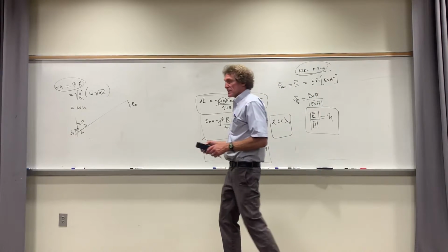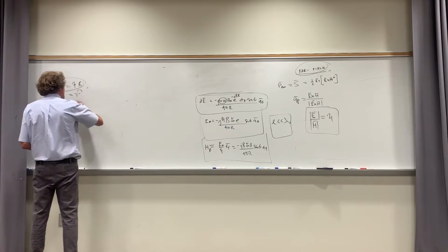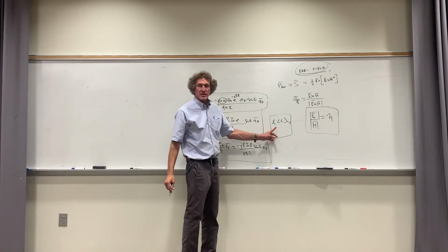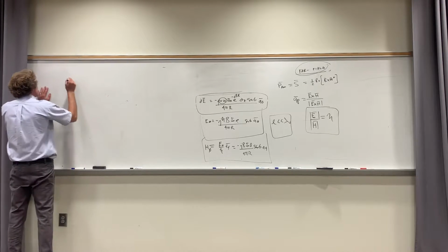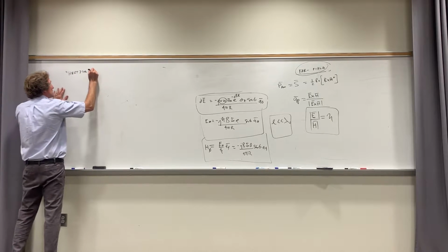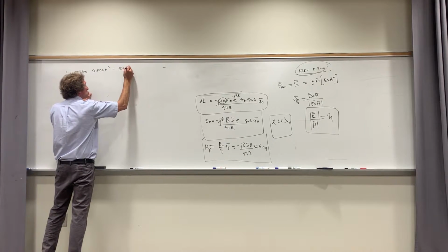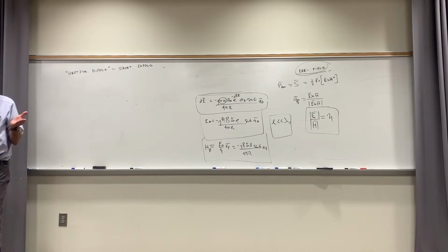Now, this is a short dipole, by the way. Even though it was infinitesimal at first, if I make the stipulation that the length has to be much, much less than lambda naught, and it's lying on the z-axis, they term this a Hertzian dipole, or a short dipole. I personally like the term short dipole. Hertz gives too much credit to a person. It's not a rental car agency either.